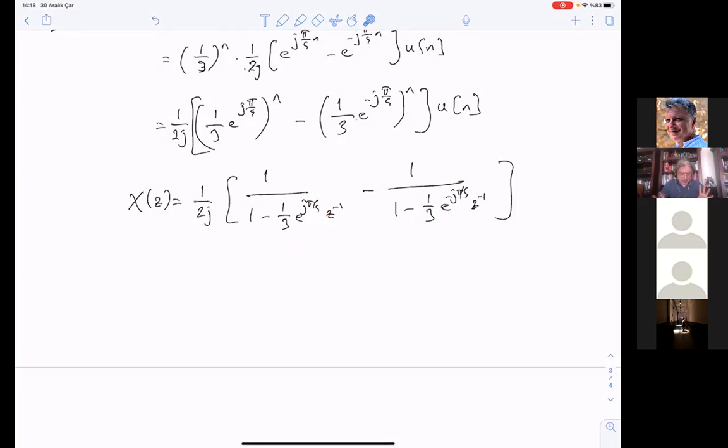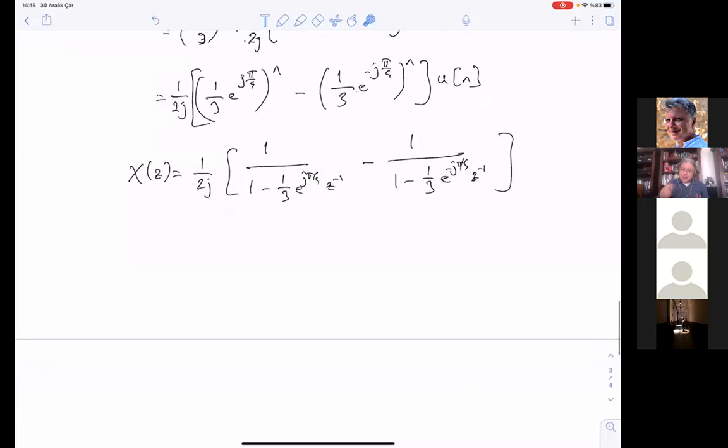And if you just leave it like this without any further simplification, an engineering student in electrical engineering should be able to locate them on the axis and at least tell me where the poles are. The zeros are at z equal to 0, clearly, because when z is equal to 0, the denominators of the two terms diverge to infinity, and 1 over infinity will become 0.